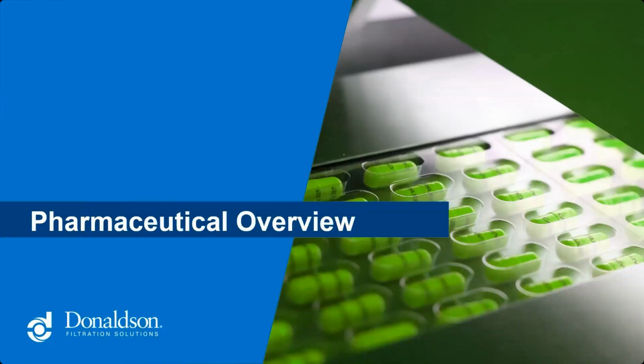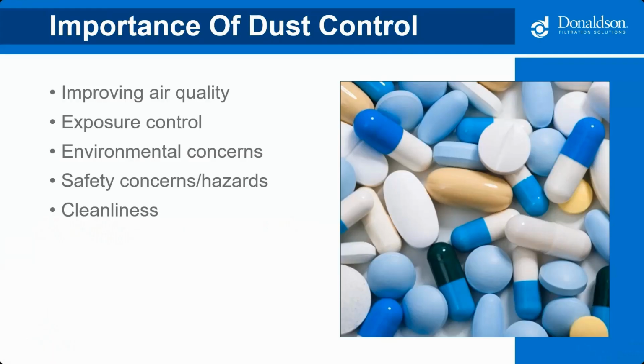Okay, so let's talk a little bit about the dust that's generated during pharmaceutical applications. Why is dust control important? Well, there's multiple reasons why it's important to control the dust, such as improving air quality. It's harder and harder to find workers today that want to come to work and work in these manufacturing environments. So it's really important to have good air quality and give them a good space to work. Exposure control is another one. We want to reduce the potential dust in their breathing zones for those who are operating these processes.